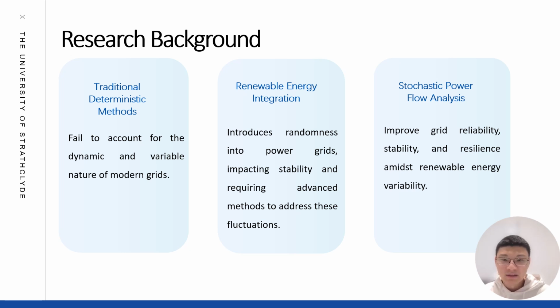Stochastic analysis accounts for the probabilistic nature of power system variables, providing a more comprehensive understanding of grid behavior. Instead of a single point result, the stochastic method produces a range of possible outcomes with associated probabilities, helping operators and planners deal with uncertainty. This approach is particularly valuable for identifying weak points in the system and assessing the impact of renewable energy integration on network stability and reliability. By addressing variability and randomness, stochastic power flow analysis enables the design of more efficient power systems.